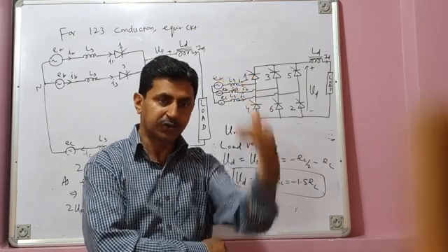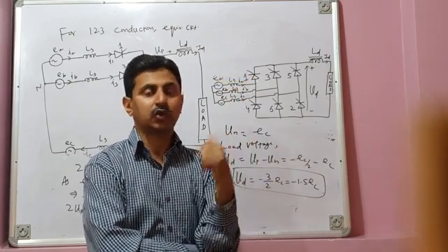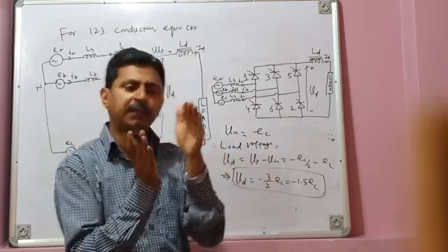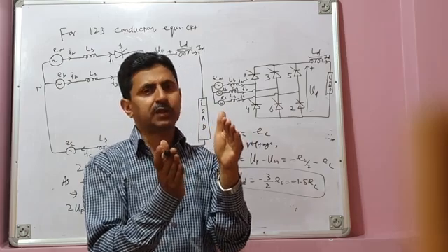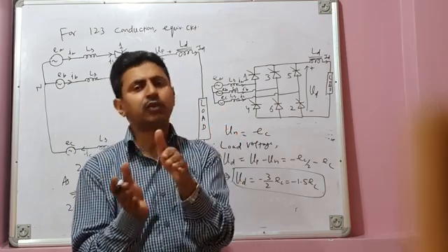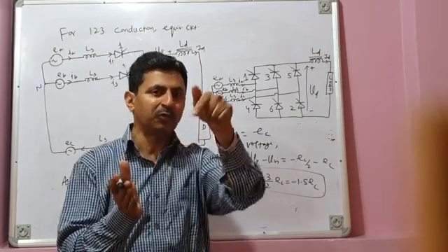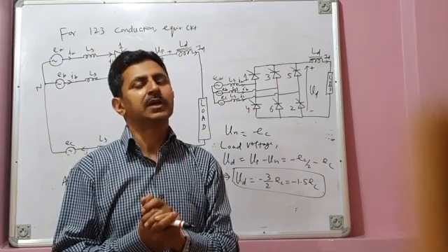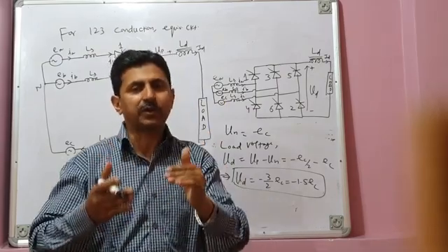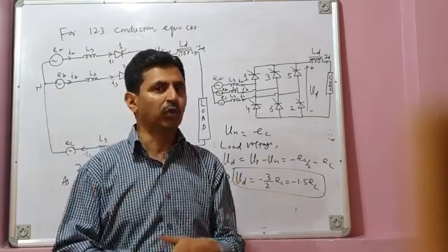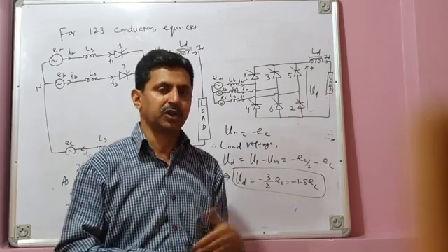So that means there is a drop in the load voltage. The load loses some voltage. Therefore, whenever there is two valve conduction, load voltage is equal to the line voltage segment. And whenever two valve conduction is followed by three valve conduction, load voltage drops from line voltage to 1.5 times phase voltage. So there is a dip, or a drop, in the load voltage. Therefore there is a loss of voltage with commutation overlap.